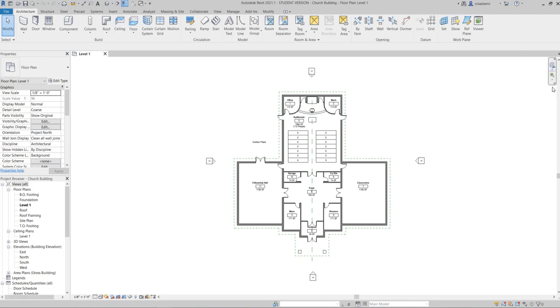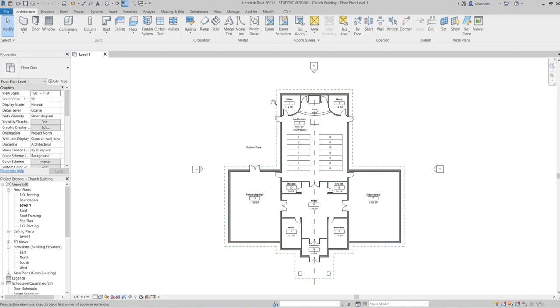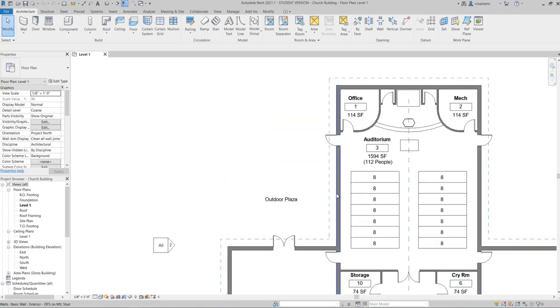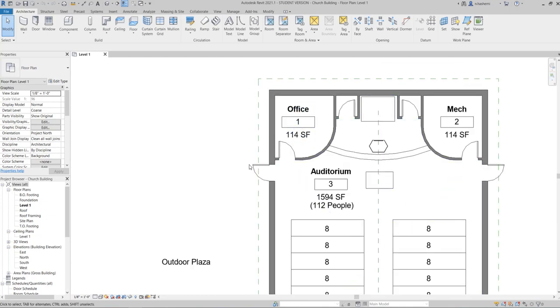Okay, so this is the navigation bar, and as you can see, when you click on this, you can see that we have different zoom options. So we have zoom in region. You'll just zoom into that part, okay? Just click on it and then select part of your drawing and it will zoom in.